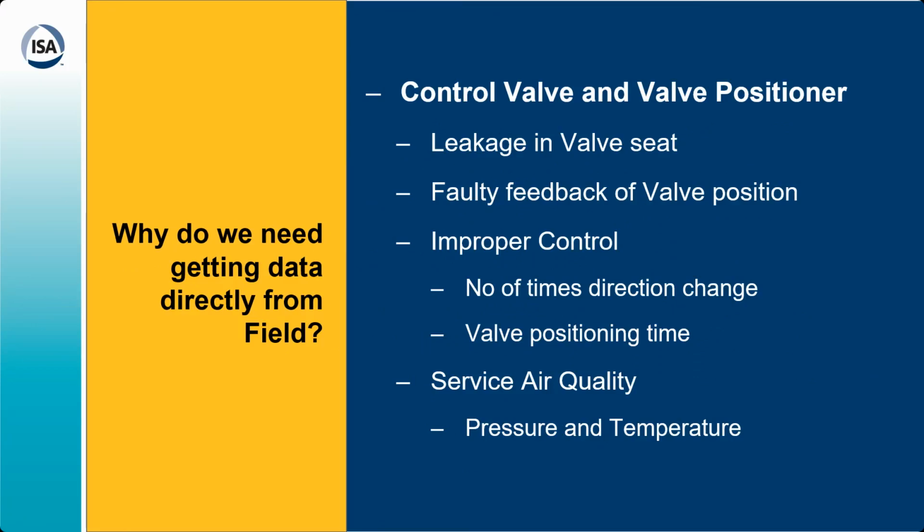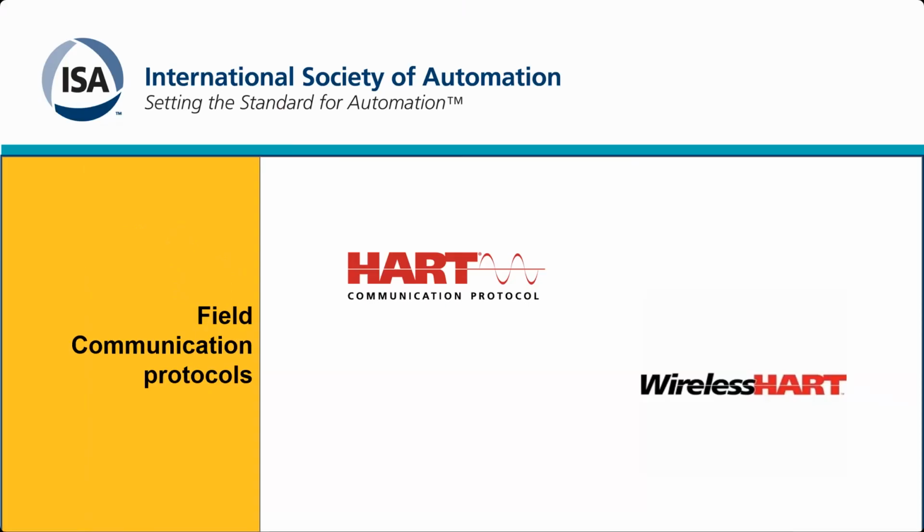In these technologies, you either have the HART or wireless HART or the fieldbus technologies. These are available in the instrument, and you can directly get the data from the instrument and take action on that. You can build a complete cloud-based instrument management system, or a complete cloud-based plant maintenance system, and by using all this data you can have effective plant performance by effectively using these protocols.